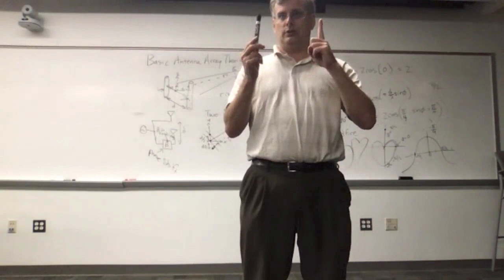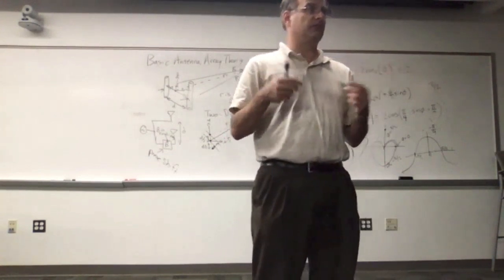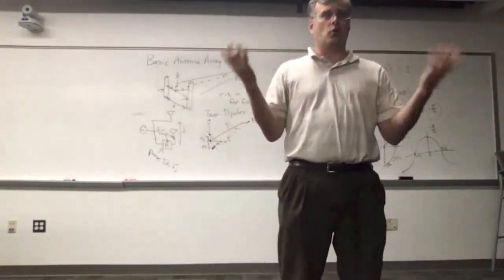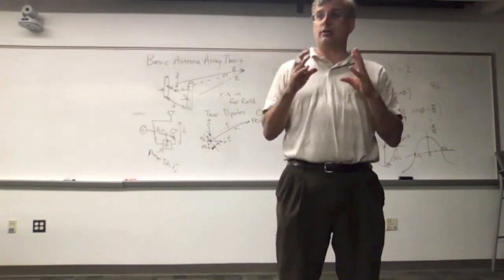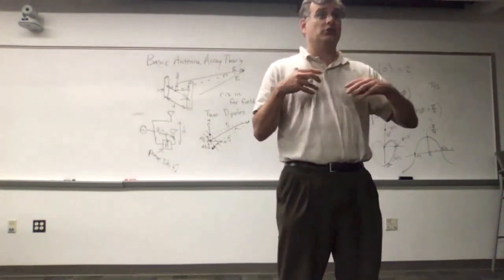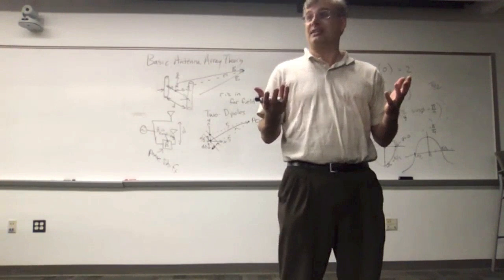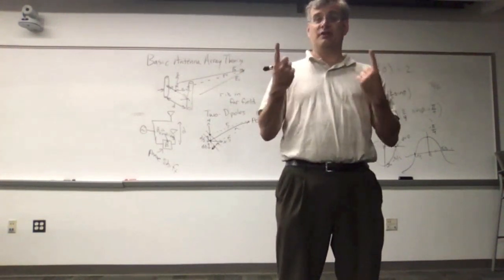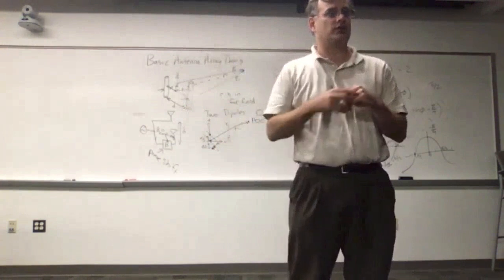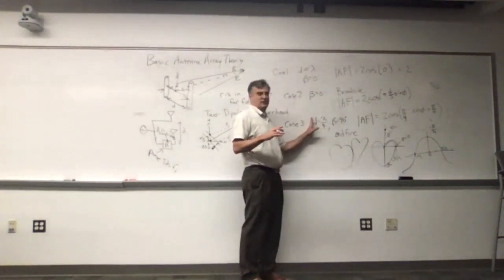If you bring two antenna elements close enough so that they are within the quasi-static field of one another, basically within about a wavelength, lambda over 2, depending on how strict you are about defining where the quasi-static field begins. If you bring those antennas that close, then you'll excite parasitic currents. One will excite parasitic currents on the other, and you will no longer have the desired excitation that you think you have. You actually get some directionality, just like a Yagi. You thought these were two antenna elements that had omnidirectional patterns. In the presence of one, it might throw the beam in one direction or the other. And so generally speaking, we don't like to put antenna elements any closer than lambda over 4.